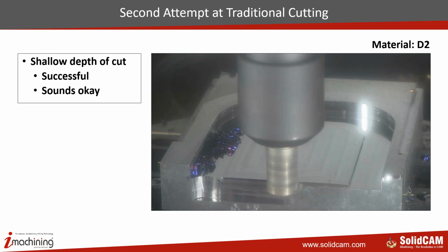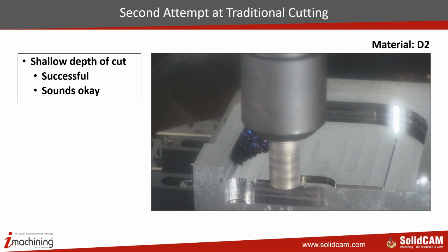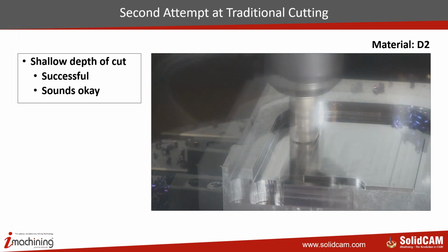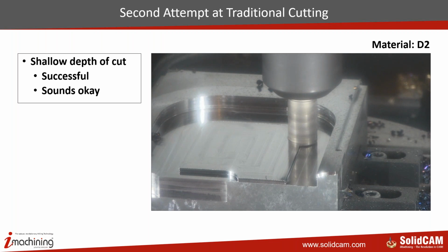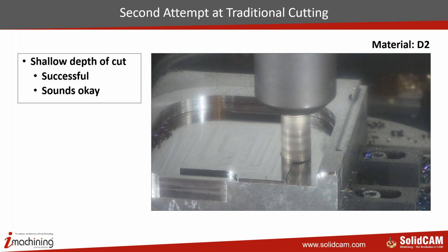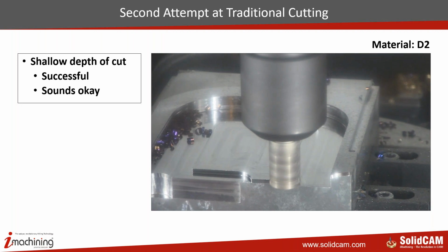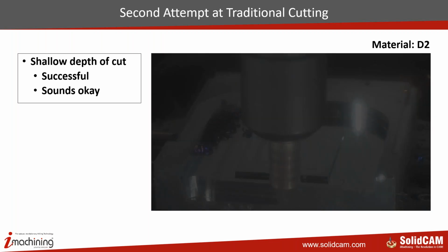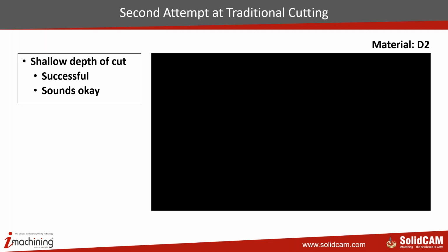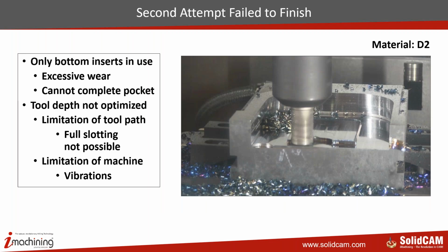Let's watch the video. From the video, we can tell the cutting is actually good. The problem is we were only using the bottom set of inserts. Let's watch the video from later in the cutting and see what happened.